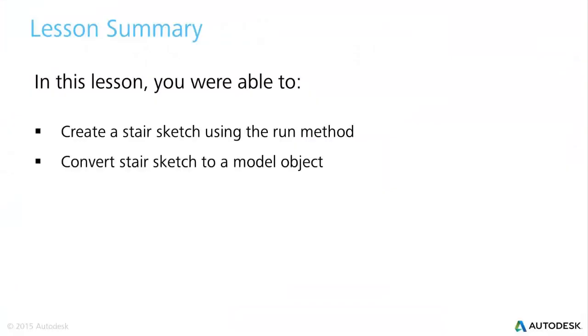Let's review the learning objectives for video 1. In this lesson, you were able to create a stair sketch using the stair by sketch method, and then we used the run technique to specify a start point and an end point. We then converted the stair sketch to a 3D stair element. With that, let's take a look at Autodesk resources that are available to you.